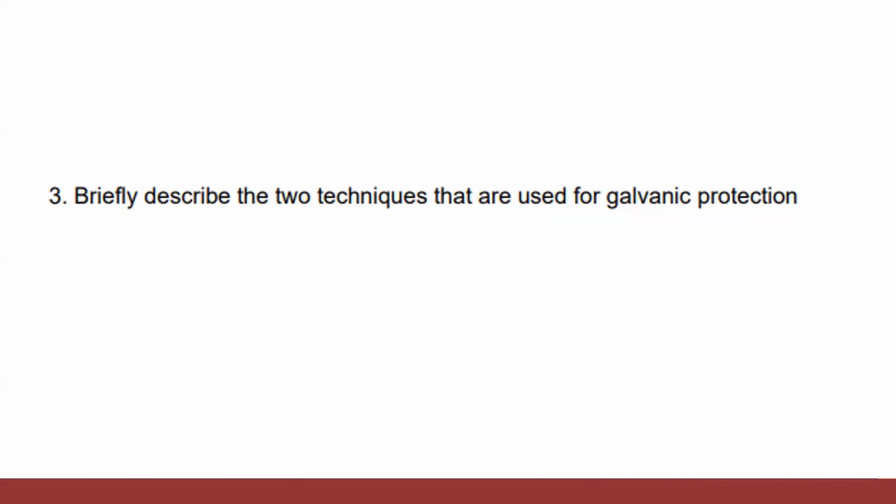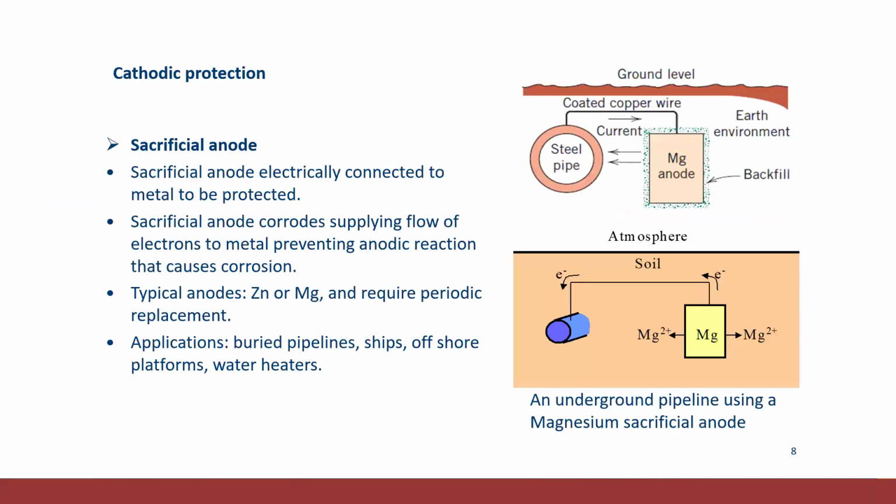Corroding the anode, the cathode is protected, isn't it? By purposely selecting an anode, and making the structure that we need to protect the cathode, we can protect it, isn't it? For example, we have a steel pipe. If we want to protect it, we can select a material which is an anode.